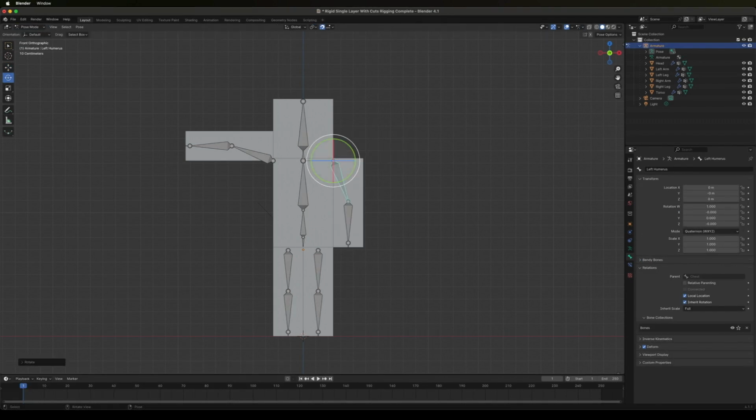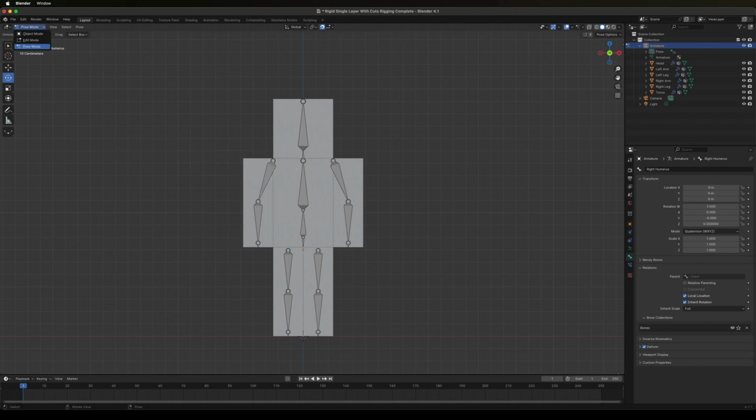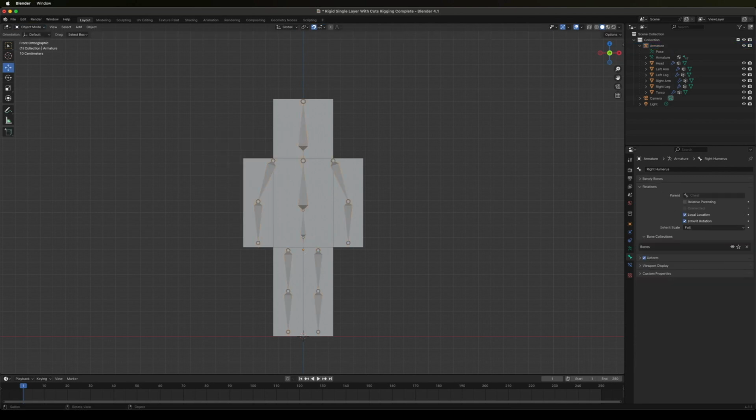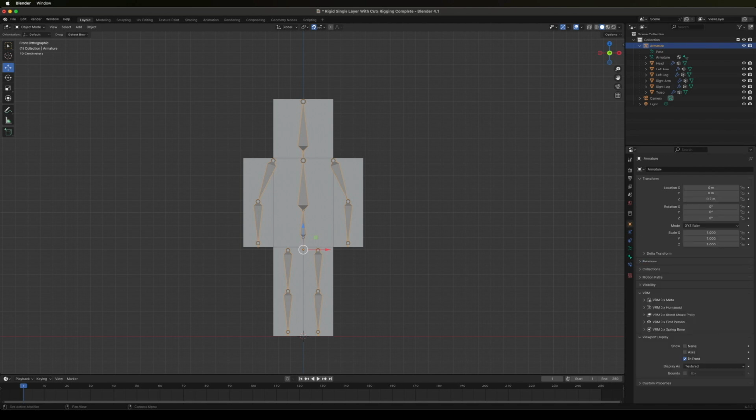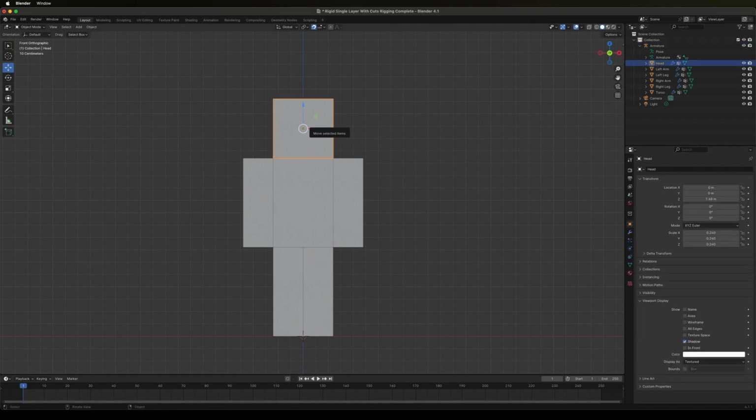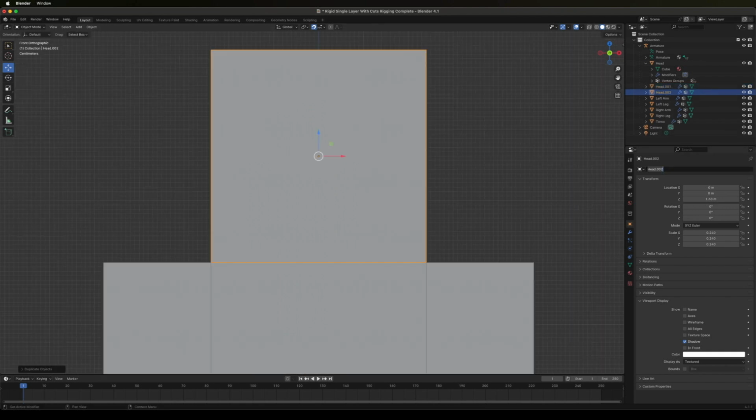Now, we'll work on reintroducing the second skin layer in a way that is supported by the rigging. Firstly, we'll return the model to its original stance and hide our armature, since all we're looking for is being able to manipulate the base layer objects. We'll start with the head and duplicate the head object, much as we learned to do in the previous tutorial part. We label it appropriately and set the relations to the head.